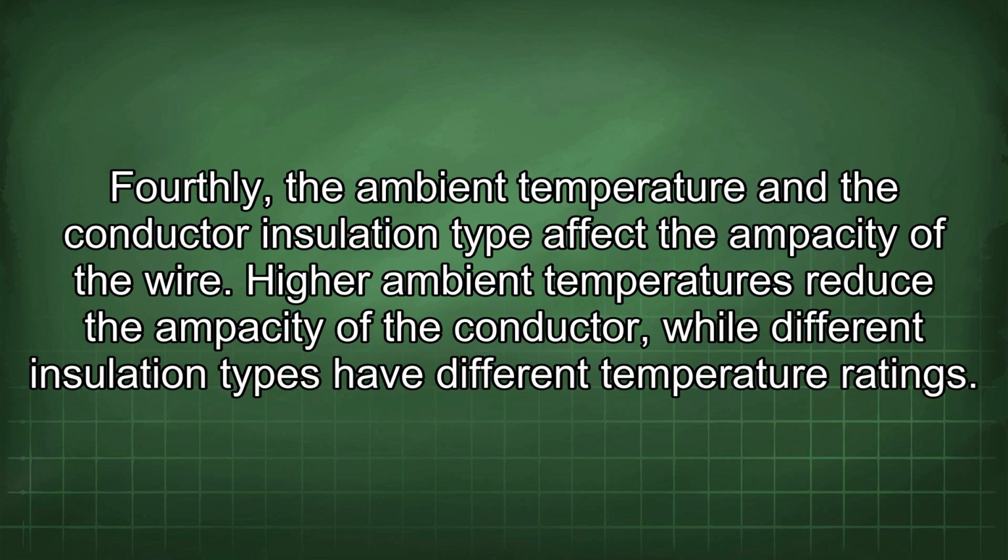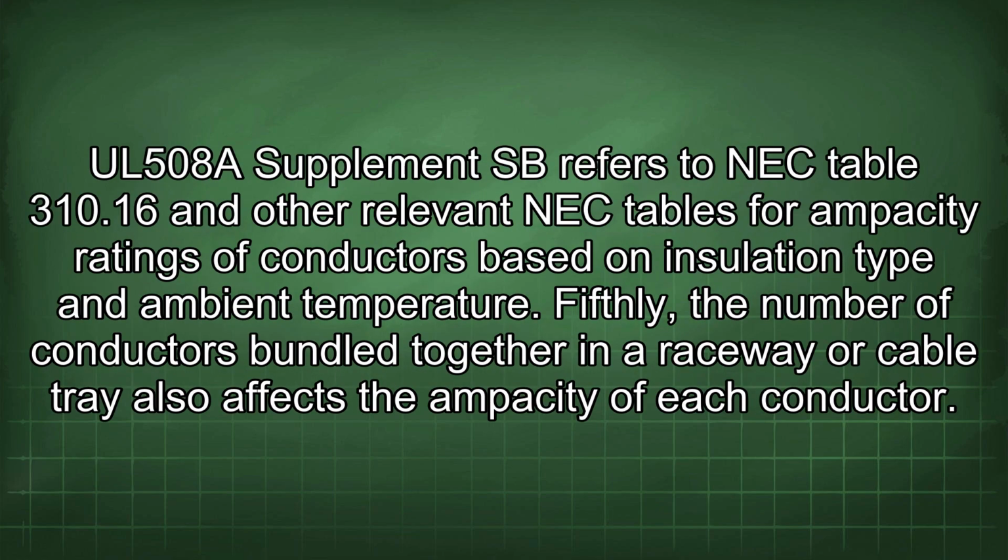Higher ambient temperatures reduce the ampacity of the conductor, while different insulation types have different temperature ratings. UL508A Supplement SB refers to NEC Table 310.16 and other relevant NEC tables for ampacity ratings of conductors based on insulation type and ambient temperature.